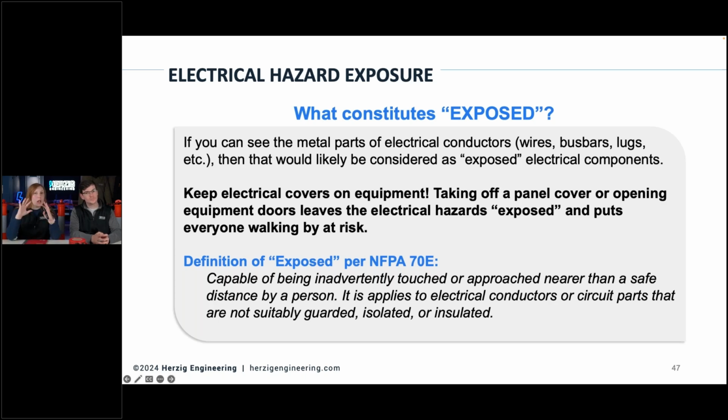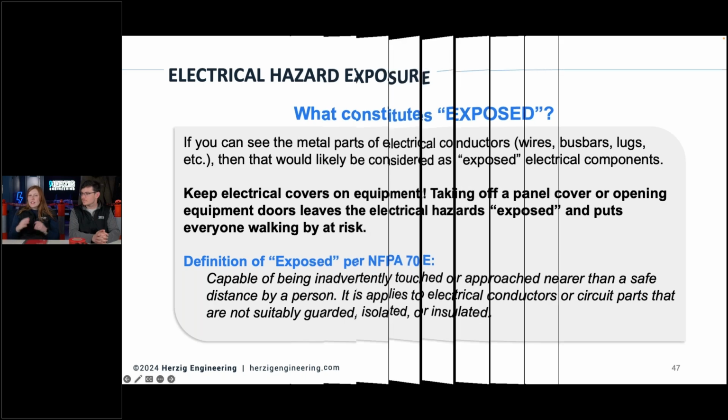Same thing with those plexiglass covers. Even breaker blinks. Arc flash hazards are how hot? Tens of thousands of degrees. They're going to melt that little plastic real fast. Take a panel board. You've got a few breakers and then you've filled in those little plastic tabs for the breaker blinks so that you don't accidentally touch, and stuff's not accidentally falling in. Great. Still, if there's an arc flash, what's going to happen with those little plastic tabs? They're melting, getting blown off. So what is exposed here? Got to make sure.